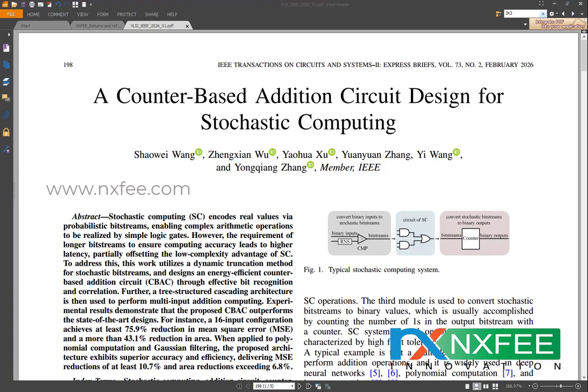In this work, the n-bit input counter-based addition circuit, meaning the CBAC architecture, is employed as an efficient hardware building block for the CNN convolution operation. The proposed implementation supports both 2x2 and 3x3 CNN kernels using the same scalable CBAC architecture, eliminating the need for conventional binary adders and divider circuits during mean value computation.